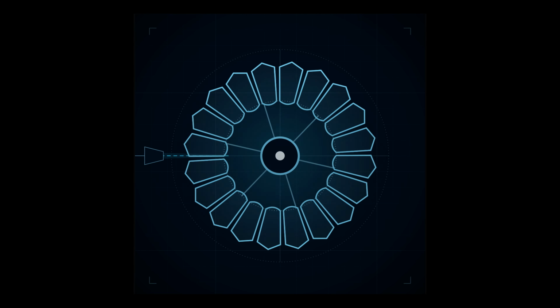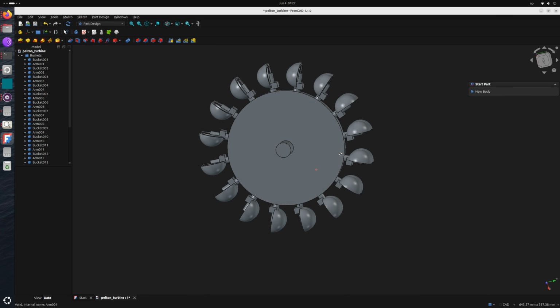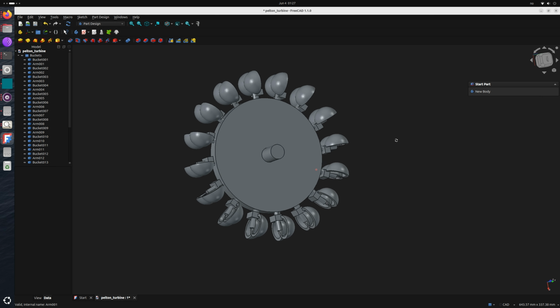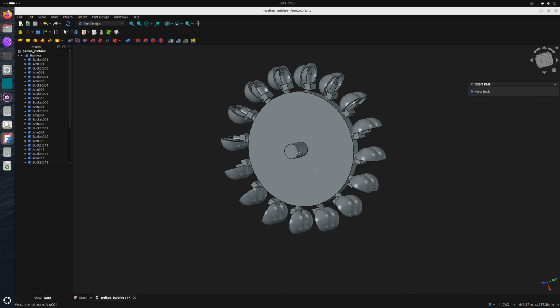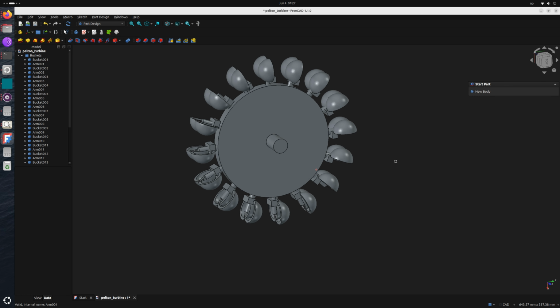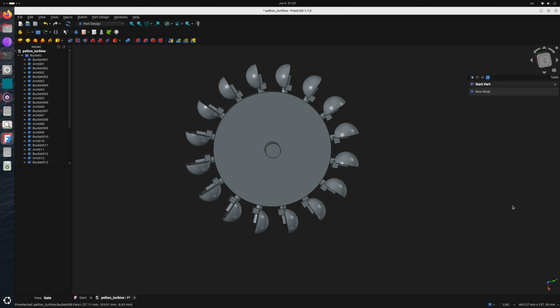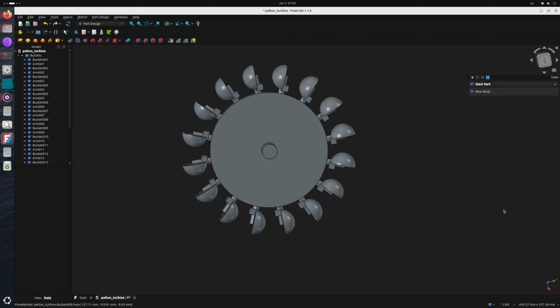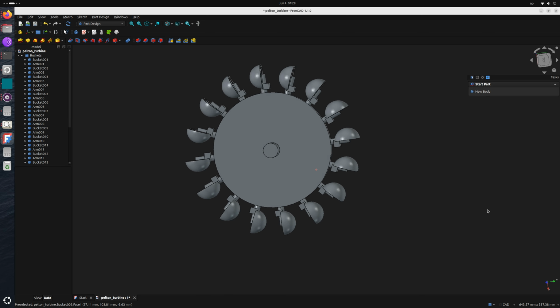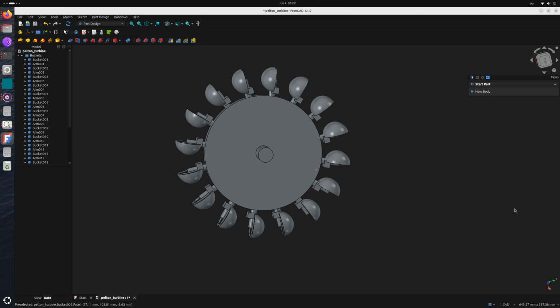Pelton, the punch. First, the Pelton wheel. In Norway, it owns the highest, steepest, and most aggressive waterfalls, because this is exactly what it needs: enormous heights. A Pelton doesn't really use pressure, it works on pure momentum. Take all that fall, squeeze it into a high-speed jet, and fire that jet at a cup on a rim wheel. The water dumps its momentum into the cup and falls away spent. It's essentially a water cannon turning a wheel.